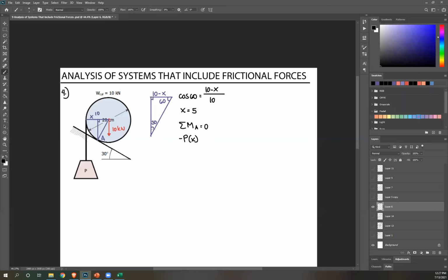What other force is there? We have this external force, rotate about A, that's clockwise, so plus 10. Perpendicular distance is this, right? And that's just 10 minus X. There's no other external force. Remember, whenever we're creating free body diagrams of the entire system, we're only including external forces and reactions at support. Technically, there's no support here, so there's no reaction to solve for. So just equate to 0.